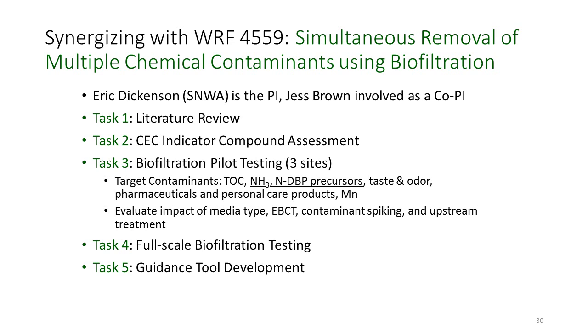The first part is really being handled by Scott and his crew. It's a literature review, really trying to understand. Jump in, Scott and Oren, anytime. There's been so much work done on biofiltration, in particular in the last 10 years, in characterizing removal of multiple contaminants, a lot of trace organic contaminants. So this first task is really gathering as much of that information that's already been gathered: the research that's been done, the kinetics, the coefficients of degradation, the removal rates under different conditions.